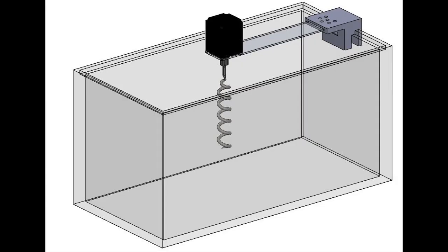Our experimental setup consisted of a cantilever beam that had a stepper motor at its end. This stepper motor held a helical coil inside a viscous fluid. We aimed to measure the deflection of this beam as the fluid exerted a force on the coil. Our first iteration had a strain gauge to measure the deflection, but we ultimately decided to use a laser and a mirror to have a more granular and less noisy measurement.